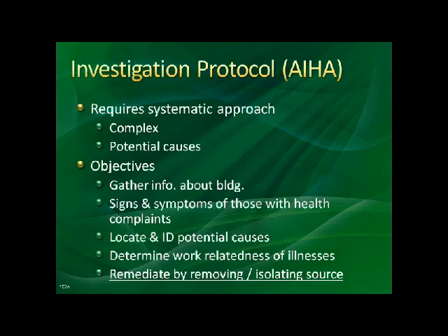There are investigative protocols. In our courses, we teach many different types of industry-recognized and adopted protocols, one of which is with the American Industrial Hygiene Association and IICRC S520. In any type of training that you go for, you need to have some type of protocol that requires a systematic approach and has an objective. You're going to gather information, do client interviews, locate the cause, determine whether there could be a potential problem, get it remediated, and isolate the source.